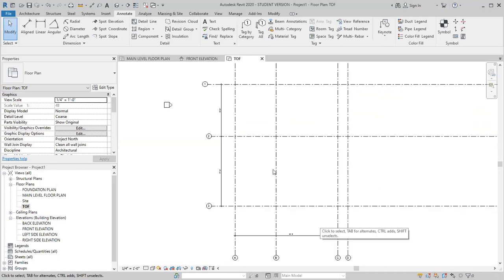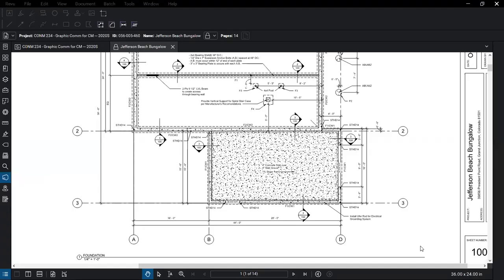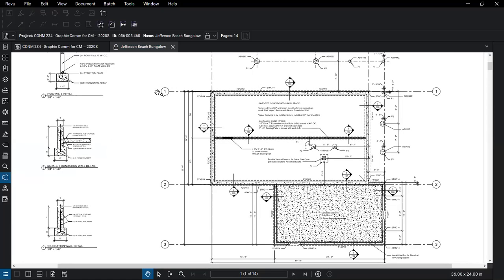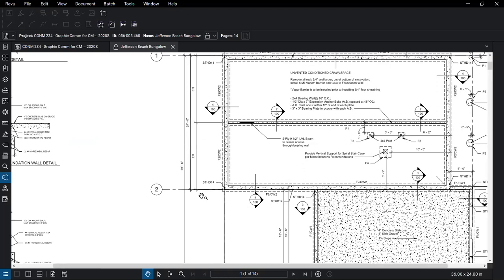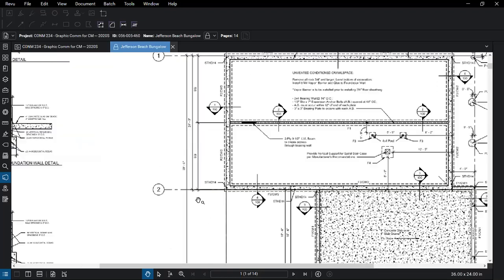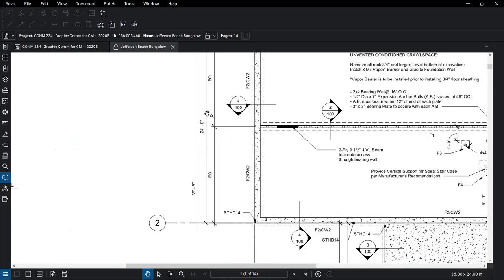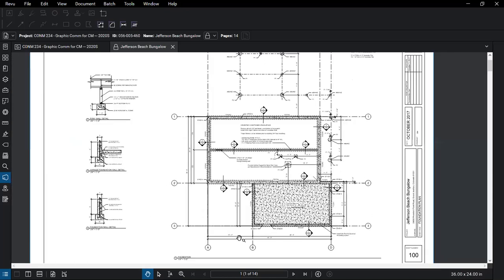Now what we're going to want to do is line up grid lines 1, 2, and 3. So once again, let me go back to the drawing. And when I look at the drawing here, grid line 1, we're saying, is in the absolute correct position. There's actually 2 dimensions I'm looking at. Going from grid line 1 to 2, we can see off of our dimension right here, we're at 24 feet.